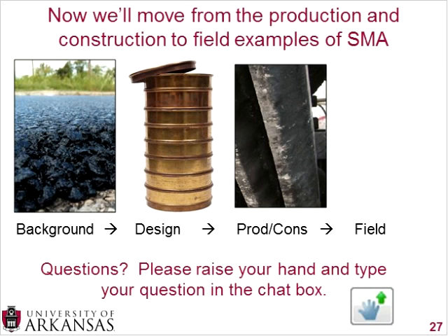So the question is, is weather a consideration? For example, high humidity, low humidity, temperatures, all of that. I did not read anything about humidity in particular, and actually I didn't read anything individually about weather as well. I think a lot of the projects I read about were under ideal conditions. It's a new product. You don't want to go out in unideal conditions. I would assume that it's a little more difficult to lay this as the temperature decreases because, again, thinking about this compaction, with the high air voids, a lot of air will move through here quickly.